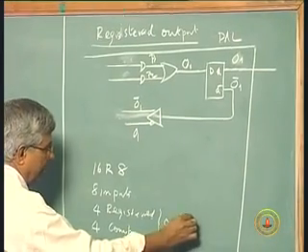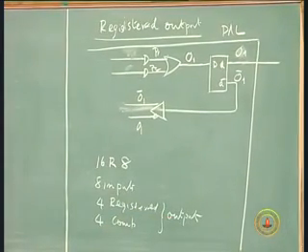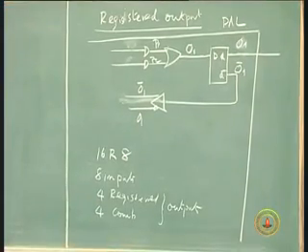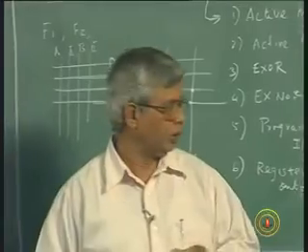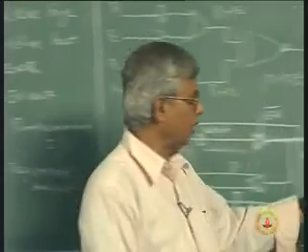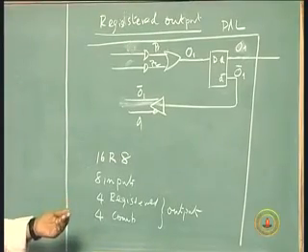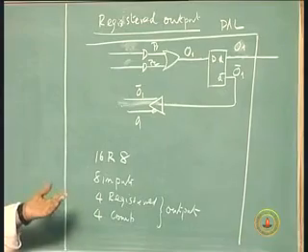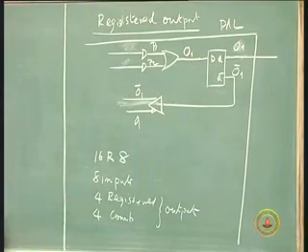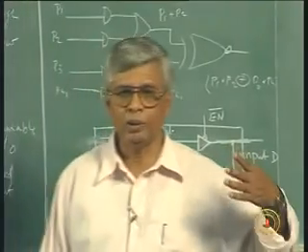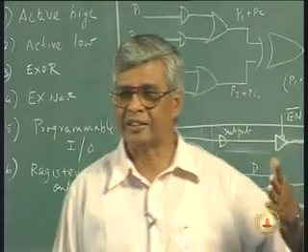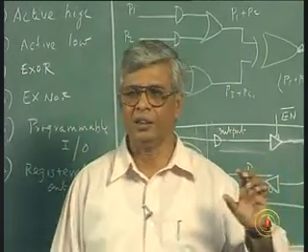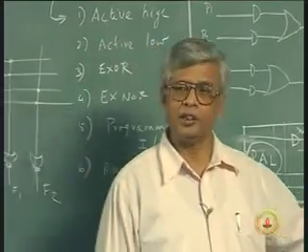Because you have to go into details of how many OR gates for each, how many connections to each of these OR gates and all that. We will not get into this. So this is also possible. You can select an IC with 4 registers, 4 non-registers as outputs. Then 8 inputs can be combined. So with up to 4 state variables, you can have 16 states, isn't it? A sequential circuit with up to 16 states can be implemented using a single IC. If you want more, of course, there are 8 registers also available.